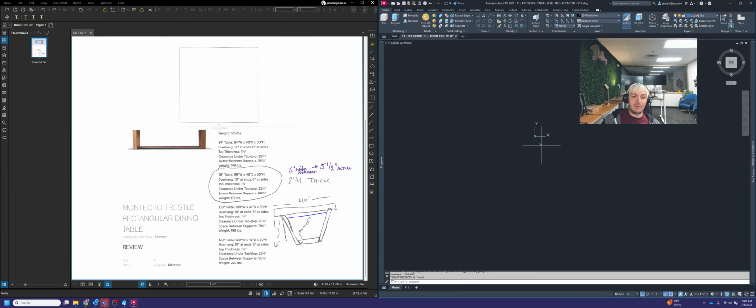Once you've done that, it will hide all of the rest of that grid, and therefore AutoCAD doesn't even know that it's there right now. It actually is there. I can type unhide or unisolate and it will bring it right back. But right now I'm trying to avoid seeing it because it will slow down my computer. I don't really want that.